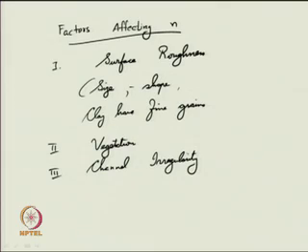If your channel is irregular, if the cross section of the channel is being changed abruptly, that is, all of a sudden it gets reduced or enlarged, these factors will affect the roughness coefficient considerably. If the transition is smooth, you will observe that your roughness coefficient will not get affected that much, but if there is a sudden hump or sudden restriction in the width, that may affect your roughness coefficient in a high